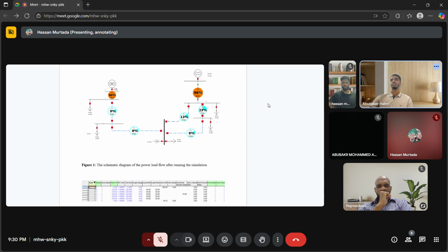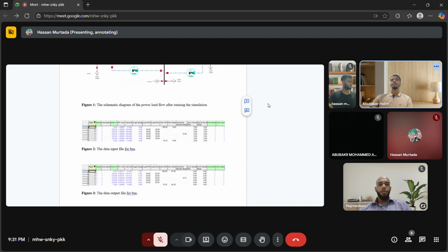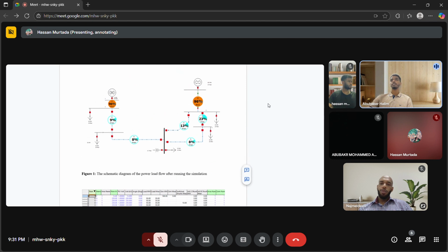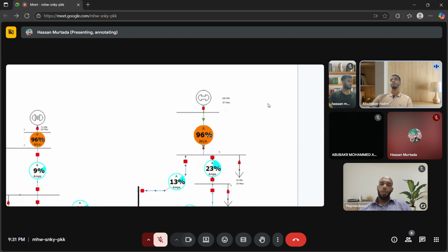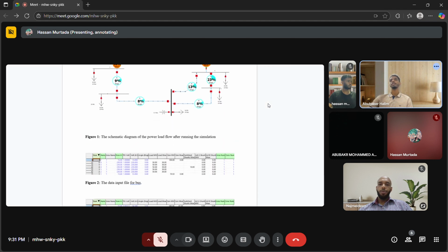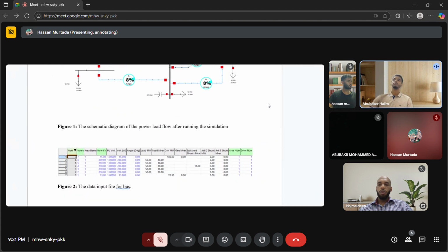Transformer 1, T1, on the left hand side is 100 MVA, and transformer 2 is 200 MVA, and the generator at bus 7 was limited to plus or minus 87 MVAR reactive capacity as specified. So, for example, here's generator 2 at bus 7. We configured the base MVA as 200 MVA and set the maximum and minimum reactive power accordingly. Similarly, T2 was entered with a reactance of 0.1 per unit and a voltage rating of 15 to 230 kV.